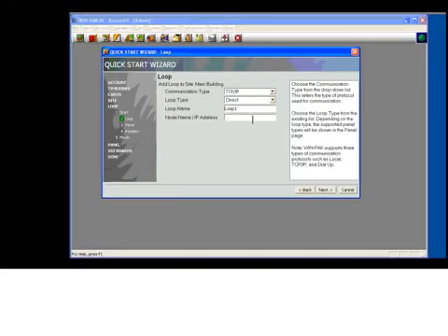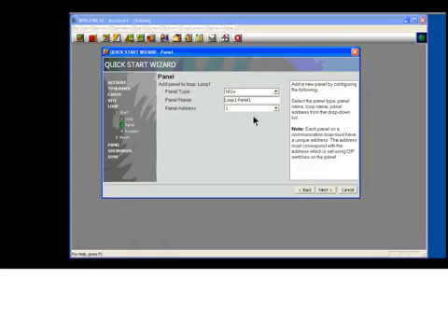So what we'll do, we're going to leave this as the name of the loop. However, down here we're going to put the IP address in here. 192.168.1.19. Now, you don't want to just make up an IP address. Hopefully you're asking your IT department what the IP address is. We'll tell it next. By default, it comes up with an NS2 Plus panel, and we'll just call this NS2 Plus panel. And that's the name of my panel.